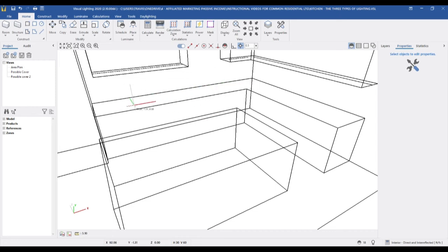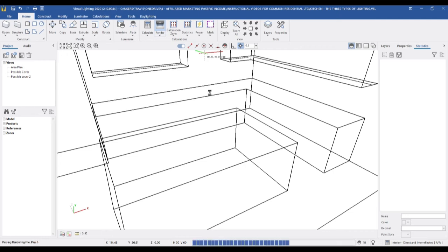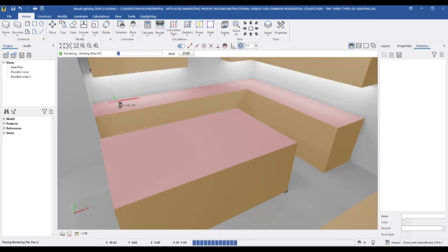So your ambient lighting filling the space might be giving you 25 to 35 foot candles, possibly different depending on the location of your countertops and where your source of lighting is. The task lighting is going to help get you to that 50 plus foot candle mark on those countertops.